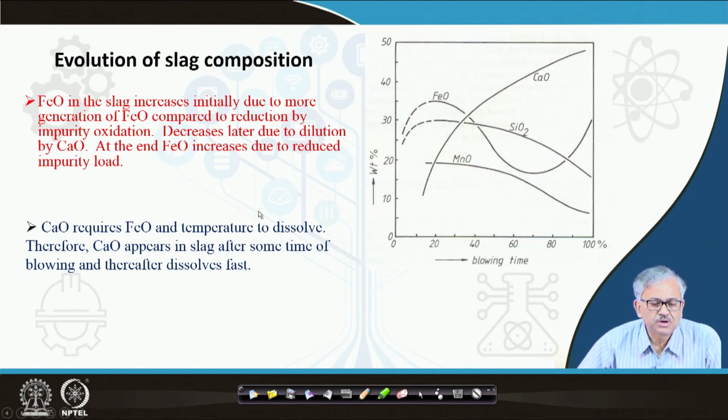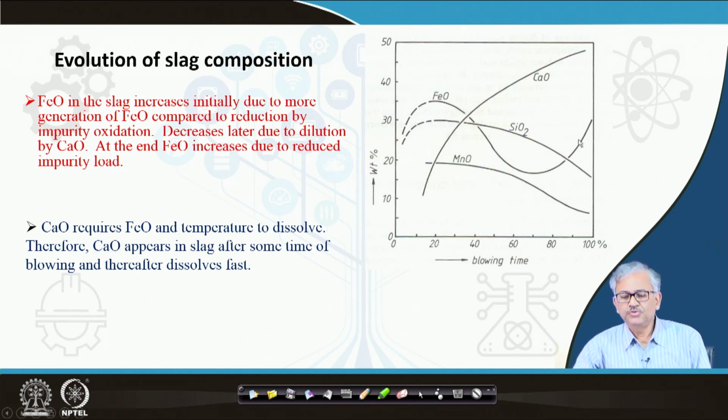Now you can see here, when the FeO increases at the latter stage, manganese also, when the oxidation potential of the slag increases, goes again to the slag phase, because of that reaction. You can see that at the latter stage the oxidation potential of the slag increases.